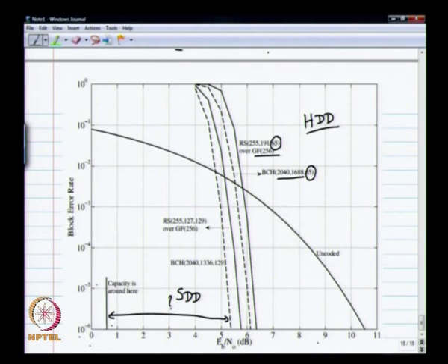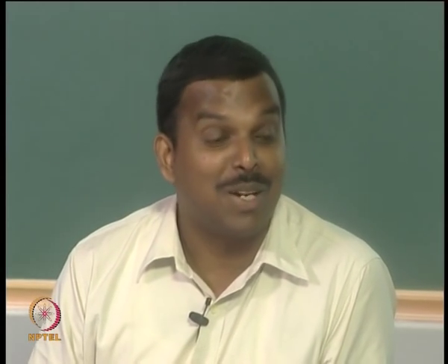In fact, there is a paper which says there is an LDPC code, low density parity-check code, which gets to 10 power minus 6, 0.01 dB away from capacity. So 0.01 dB at rate half would be almost there. In this picture, you can't see it. So the question to ask is, is there anything else left to do in coding? There's capacity, and you've achieved capacity. What more? Try to push the capacity.